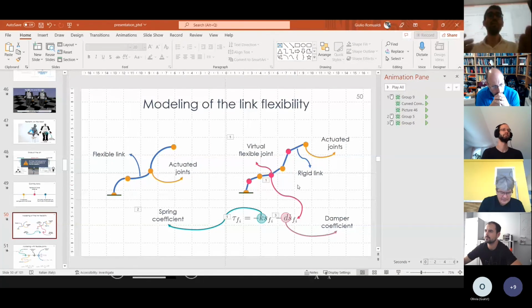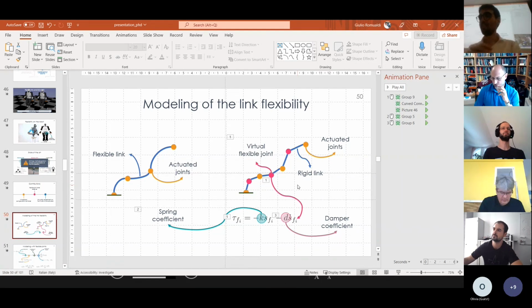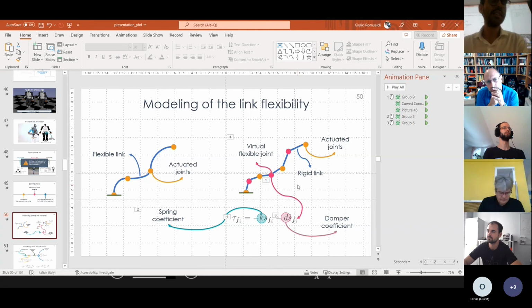At least on Talos, this is the case, because the flexibility is just inside the cross section between the root link and the hip. In that part the size of the link reduces, and the weight of the robot makes the link deflect. So in theory, yes, and it's a really nice research direction.